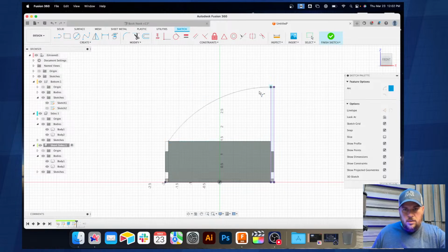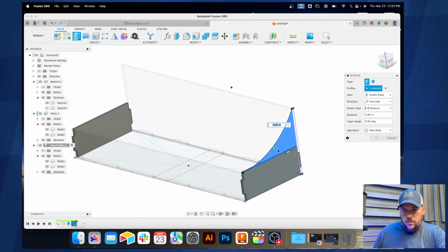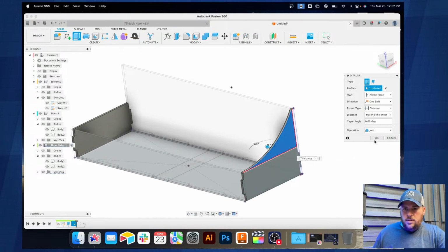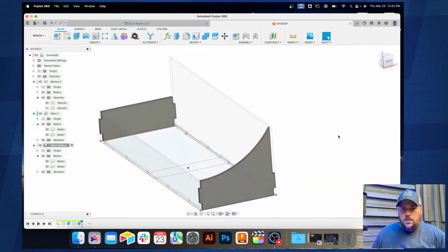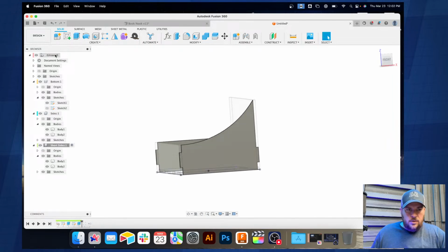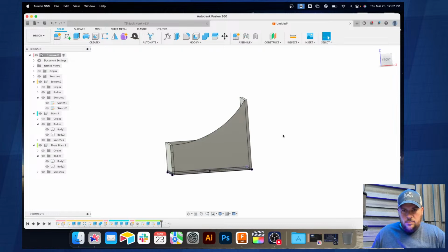I'm going to go here to here. And you see that circle with a little line on top? That means that it is tangent to that line, just like that. And I'm going to take this piece. And because the arrow is pointing in the wrong direction, it will be minus material thickness. And I want that to be one body, so I'm going to hit join. Now, looking at this, if I were to build this in real life, this piece would not really be attached right there. So what I can do is add another tab.